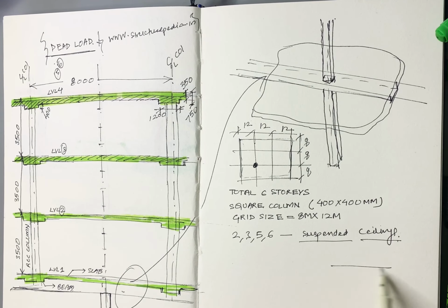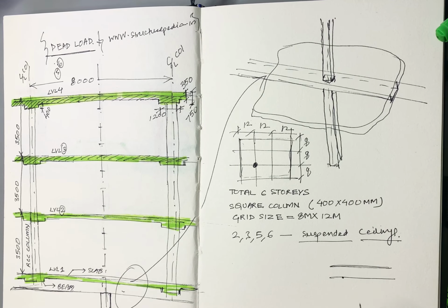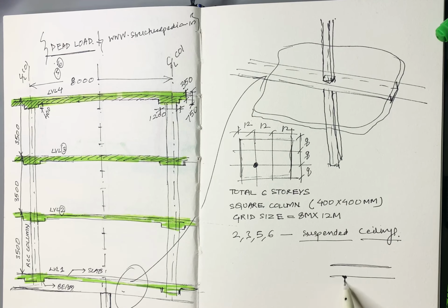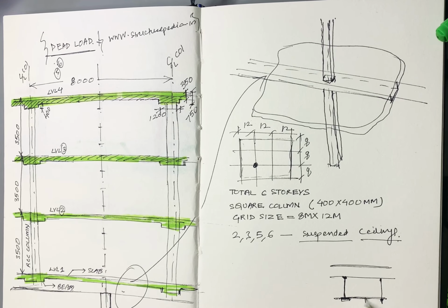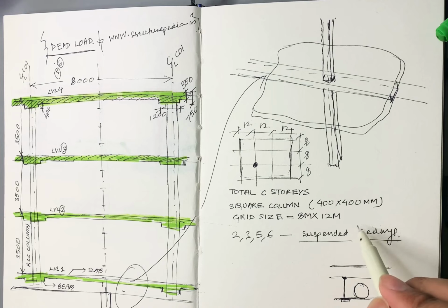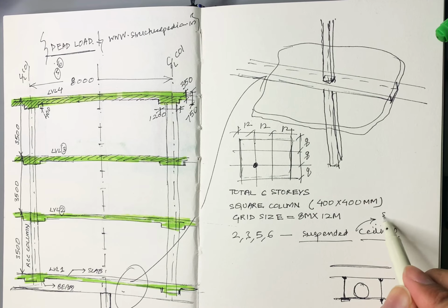First of all, if you have this slab, you might have seen that we have ducts going. It might be air conditioning, or it might be a sprinkler system. Generally we fix a hanger from the top. We have a clamping plate, something like this, and this is a steel rod hanging from the top, and from this steel rod we support the ducts. So this is the suspended ceiling system. This is additional load that is carried by the slab, which is a service load.